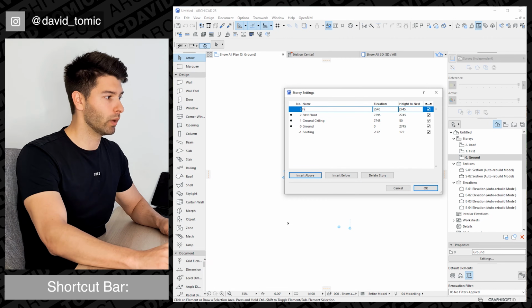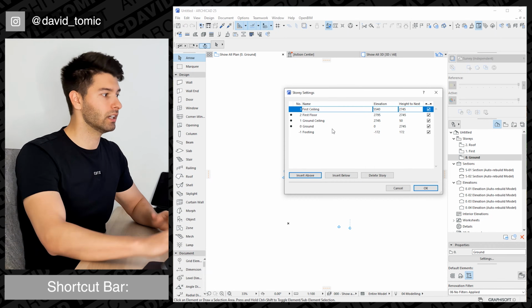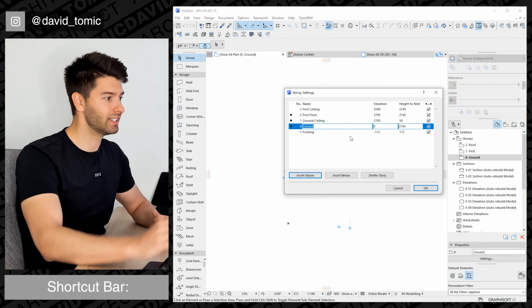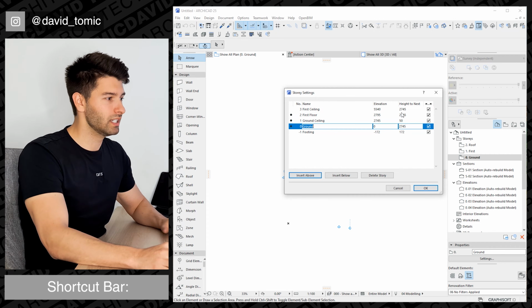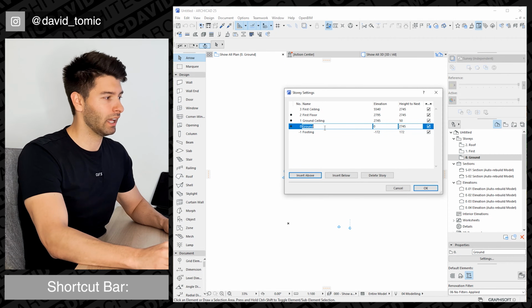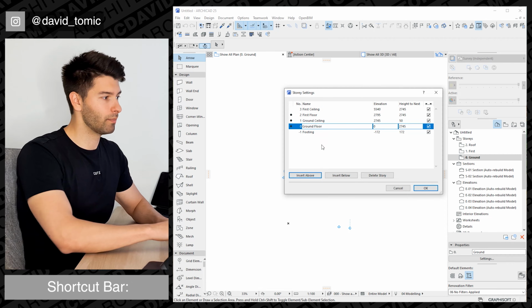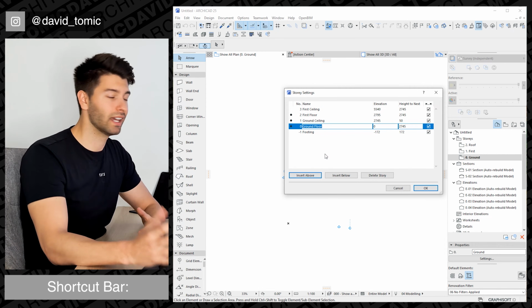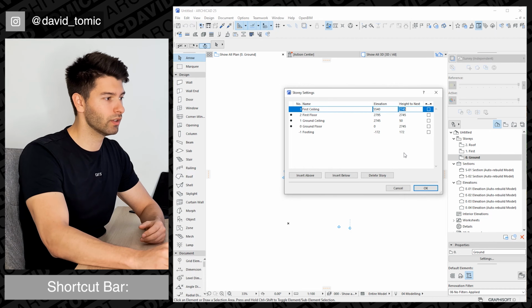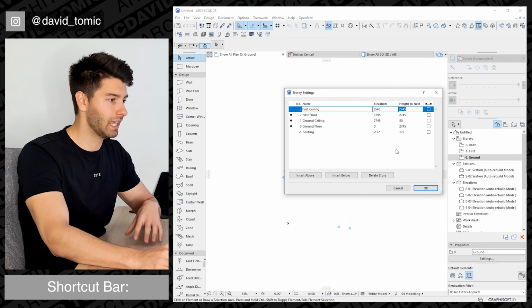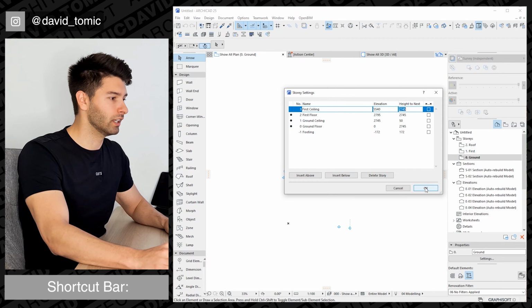And then above that, we want our first ceiling. It doesn't really matter what we do in the first ceiling above that, because that's just going to keep going on and on forever. We just want to dictate that as a number above our actual existing first floor. I'll also type in ground floor so it stays relatively consistent. Now personally, I like to untick all of those on the side for elevations. We're not going to get into that today, but it's just something I enjoy to do.